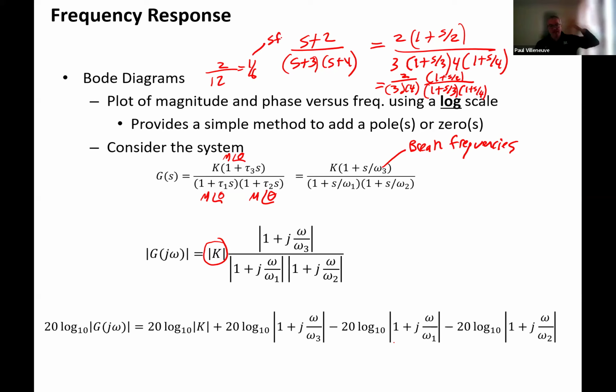And what the scale factor does is it moves the system up or down, the entire Bode plot, it moves it up or down by a scale to make that value work. And so that's why we have a K term over here. And you will note that K is purely a real term. There are no complex numbers with it. There may be a case when you actually have a pole or 0 at S equals 0, which gives you a phase shift, but that doesn't actually influence the scale factor. It only introduces that value.